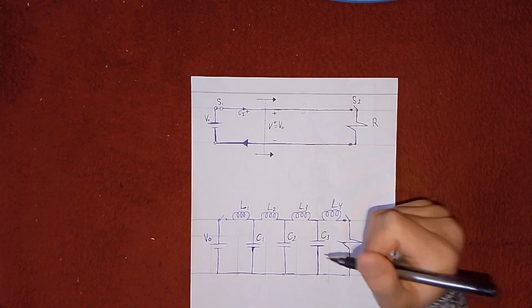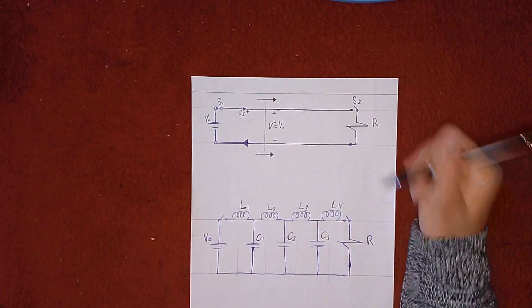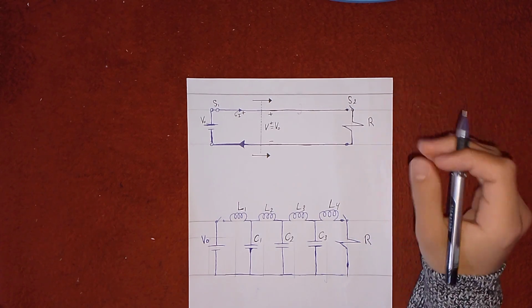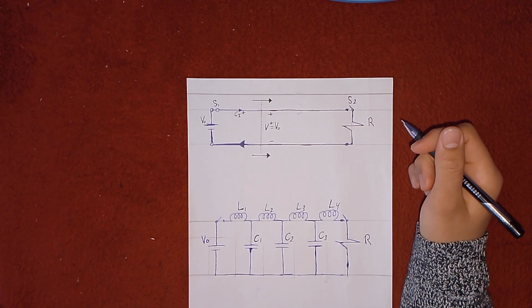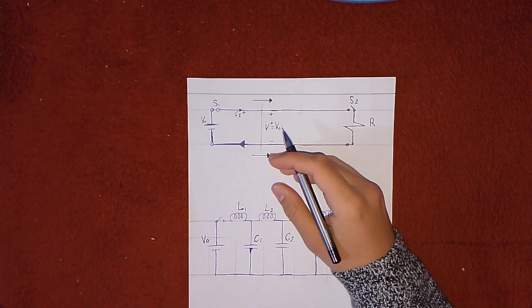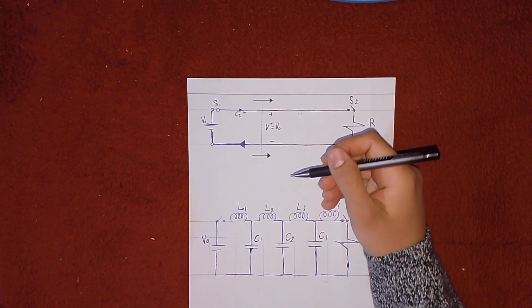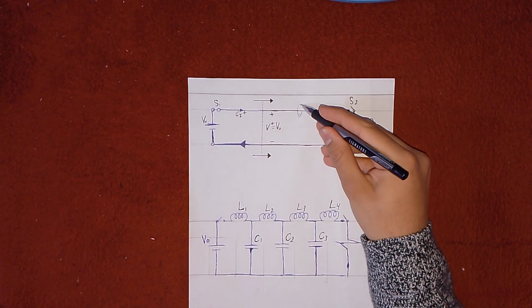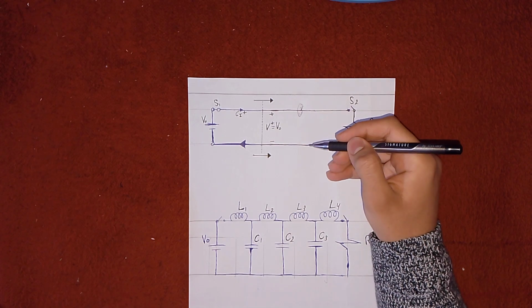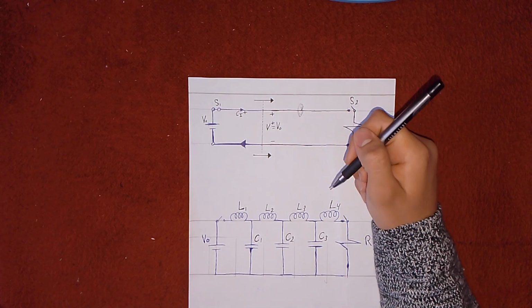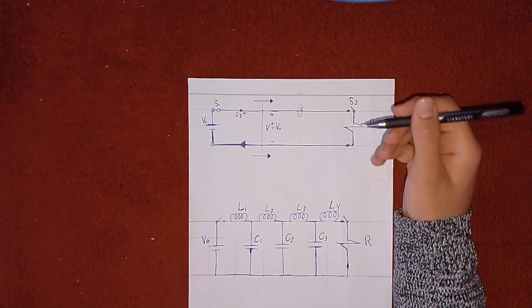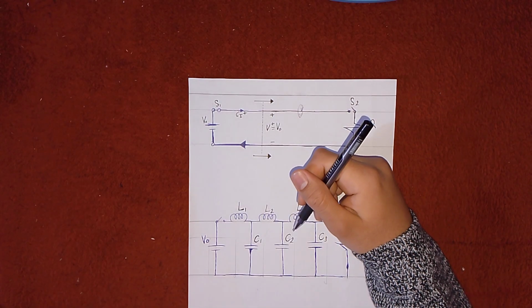This is simply a conductor, and every conductor that carries current will always have inductance, even if it is just a straight wire. Because if a current flows through the wire, a magnetic field is generated around the wire in concentric circular path lines. And this magnetic field strength is proportional to the current.